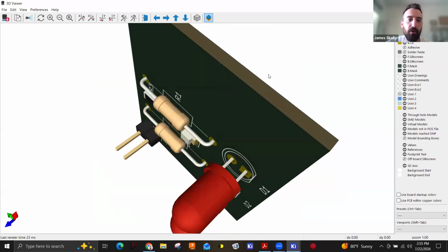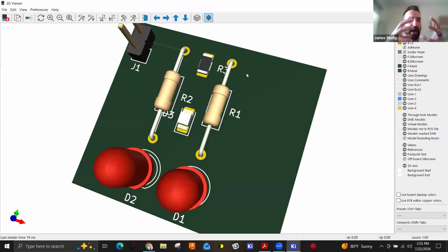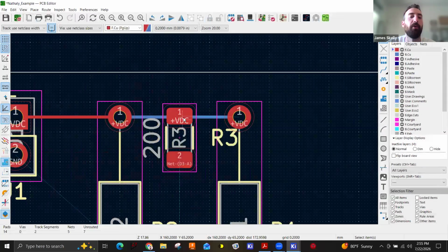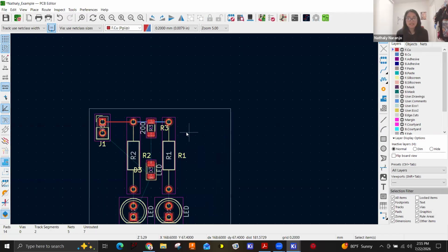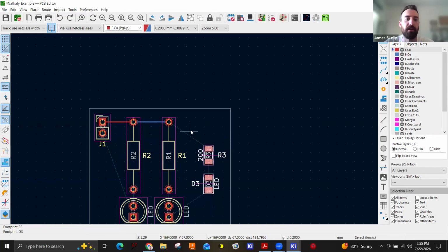So it makes compact routing very nice because if you need to route something, you can route it on the bottom of the board rather than routing it on the top. And you can now put components here. Where with a through hole part, as soon as I have a hole here, I can't do anything there. That space is fully occupied. Makes sense. Okay, yeah, it makes it look really neat. Yeah, you can make the whole thing very compact.